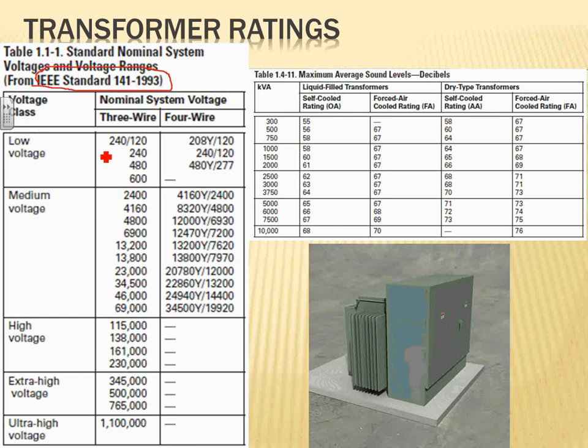power system. For a lot of us, we're probably dealing with the 4-wire system. We deal a lot with the 4-wire system, so most of us are going to be here. And we talked about the advantage of the 4-wire system versus the 3-wire system, right? A 4-wire system will give you two levels of voltage, so you can burn things at 480 if you want to, or 277 if you so decide. Versus a 3-wire system, which gives you only one voltage. That's a drawback if you need the second voltage. So that's the low voltage. I thought I'd just throw this one in.